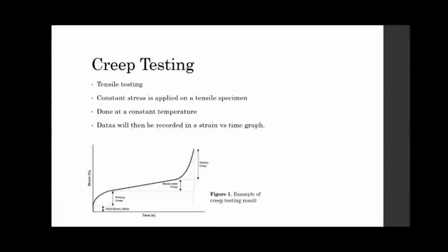This test method is used to determine a sample's creep properties when subjected to a prolonged tensile or compressive load at a constant temperature. The rate of deformation of a sample material to stress at a constant temperature is known as the creep rate. Creep usually occurs at elevated temperatures. Therefore, testing for it usually requires a testing chamber in which the temperature can be altered.